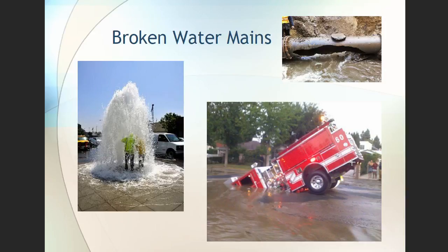I don't know if they've got a key there and they're trying to shut that thing off, but it can be a frustrating situation, especially if they're old valves that haven't been exercised. Exercising a valve is basically exactly what it says, working it up and down every so often to make sure it stays functioning.